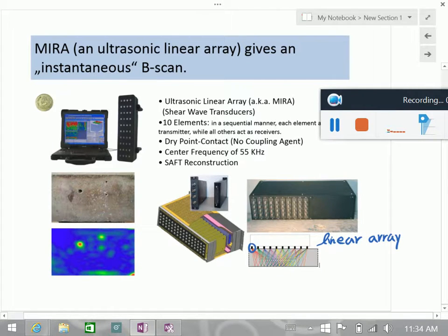If you time your senders differently, now everyone is sending just sequentially. There, you can apply delay to sending as you go from one element to the other. That would be called phased array. If you have ever heard phased array, it's when you apply delay to your senders. So you apply delay so you can focus the energy at a particular point. Make sense?